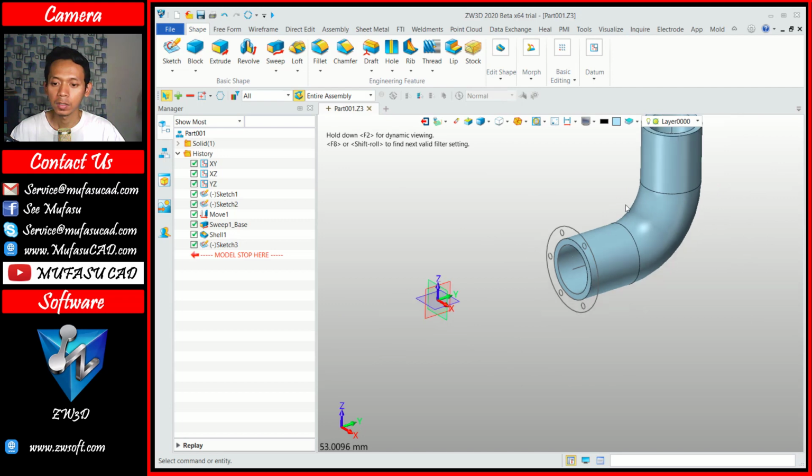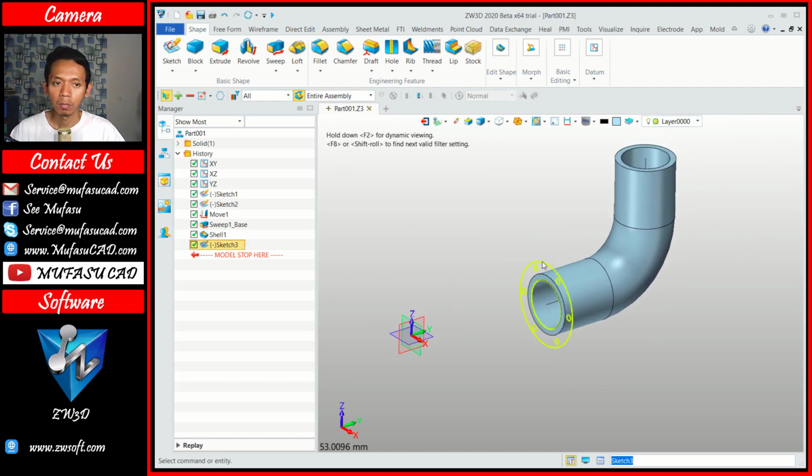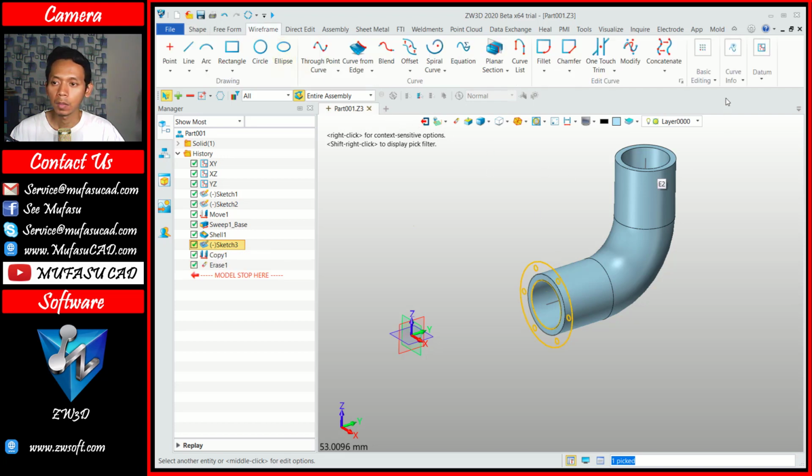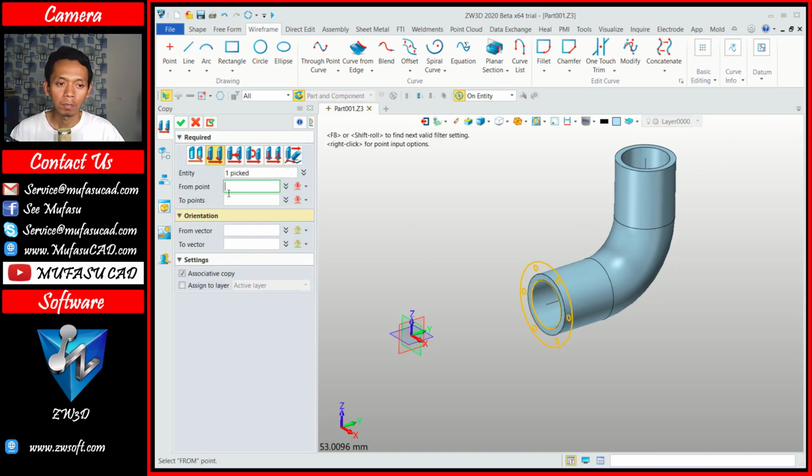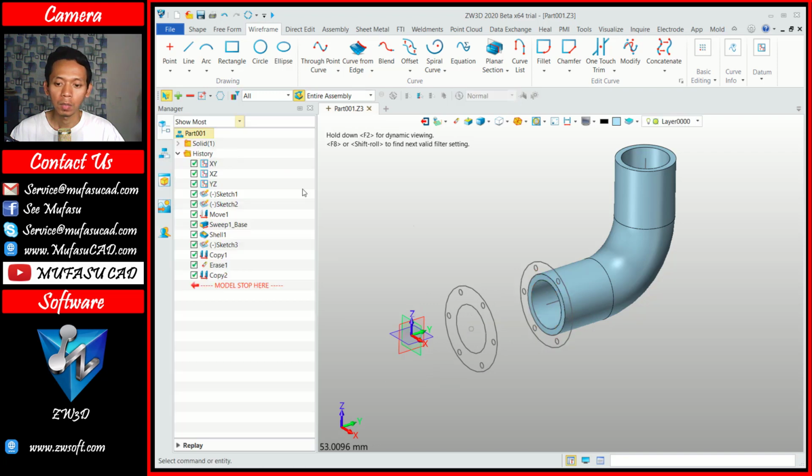Okay, we already created this sketch. I will use a copy command to copy this to this sketch. You can click the wireframe tab and then I will click basic editing. We can use the copy command. I will copy point to point. Okay, you can click at this point and then we can move to this point. You can click OK to apply.